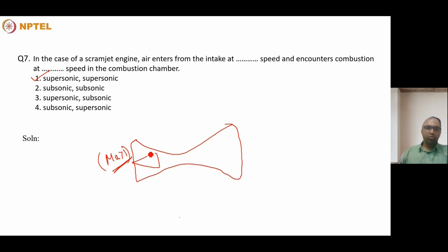So the converging section will be acting as a diffuser. So the pressure increases within this section. This increase in pressure does a function similar to that of the compressor without any moving part, due to the formation of shock waves.